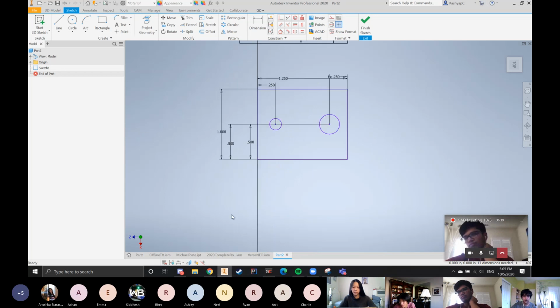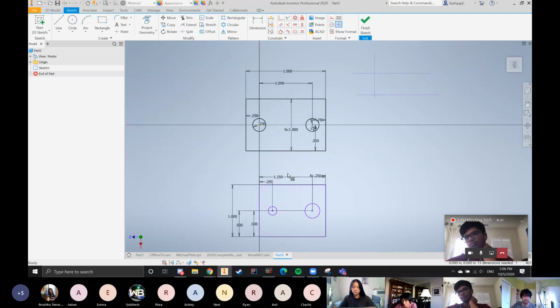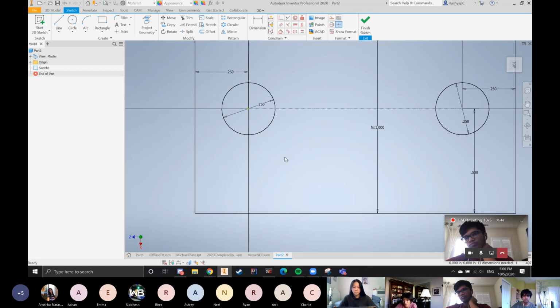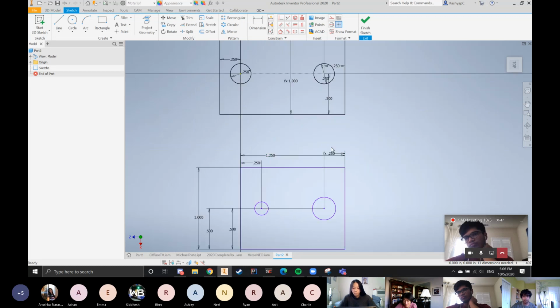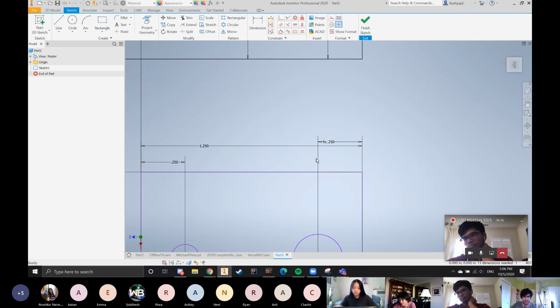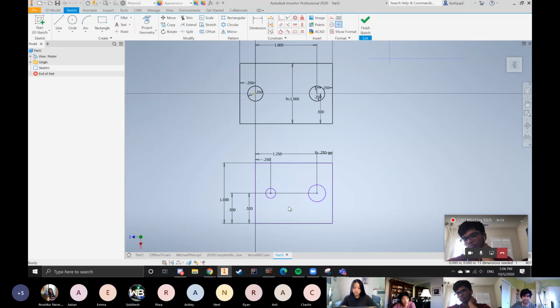So sometimes it's better to not really over-dimension a sketch, or I guess keep it more flexible. And using driven dimensions, you can create sketches that are more flexible. So if you need to make changes, you can make them easily and without errors. Hopefully, in the future, I can give you a more cohesive example for that one, like with one of the examples of a barn or a robot. But I don't know if that one's gonna be like a ramble if I try and explain it right now. But overall, yeah, those are some other cool tools you can use while sketching.